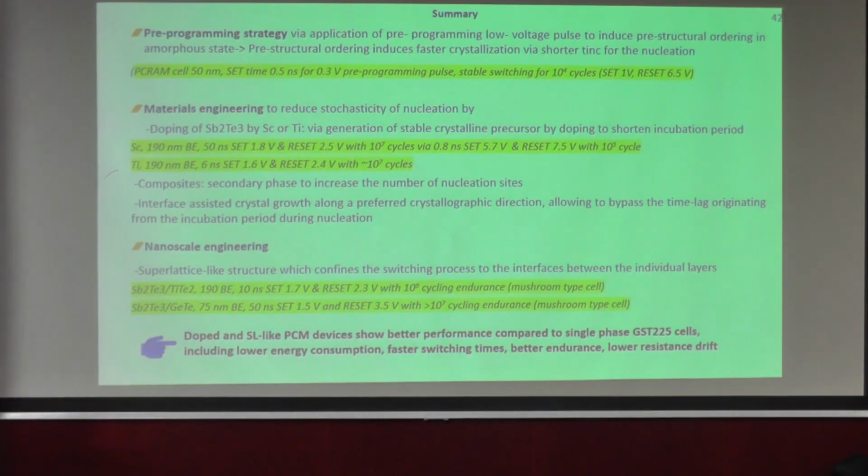So overall, doped and superlattice-like PCM devices show better performance compared to single-phase GST cells, including low power consumption, faster switching times, better endurance, and lower resistance drift.